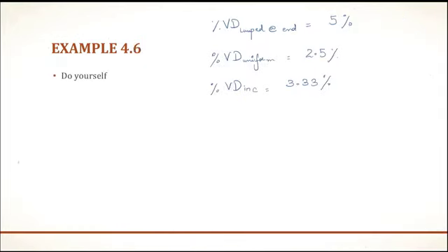So we can say that if the load is lumped at the end of the feeder, then the voltage drop will be highest, and if the load is uniformly distributed, then the voltage drop will be least as compared to all the three cases, and the voltage drop will be intermediate if you have the increasing load density.